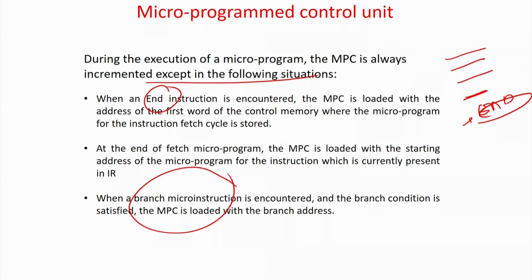It will have many small micro instruction programs for that. Like fetch will comprise one microprogram. Then add R1 and R2, after it is decoded, it is executed. That is, R1 and R2 have to be added and the result has to be written in R1. So basically that part will comprise the second micro instruction program.